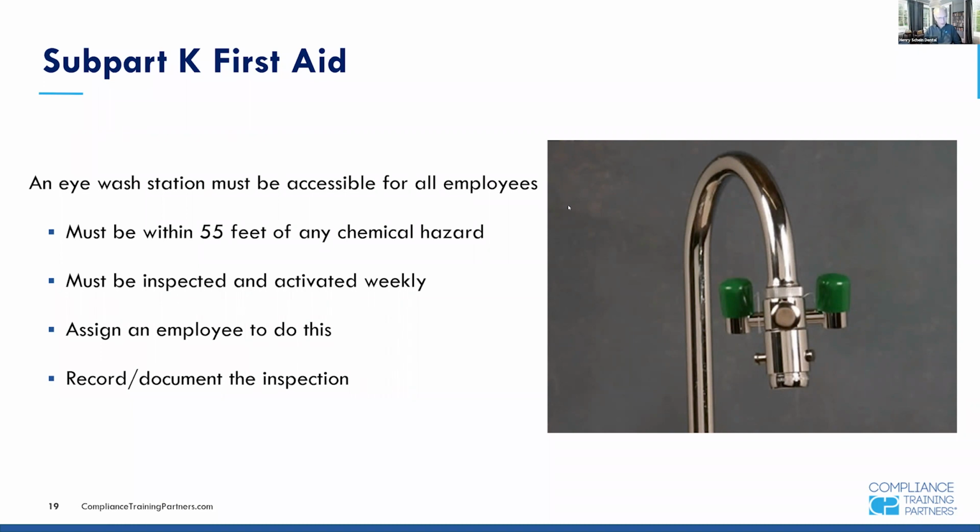You might say, wow, that's gonna take up a lot of time. No, it isn't. We're talking about a 15, 20 second a week thing. Whoever's in charge of it turns on the water, pulls the button, the caps pop off, you let it run for 10 seconds, done. And check the box.